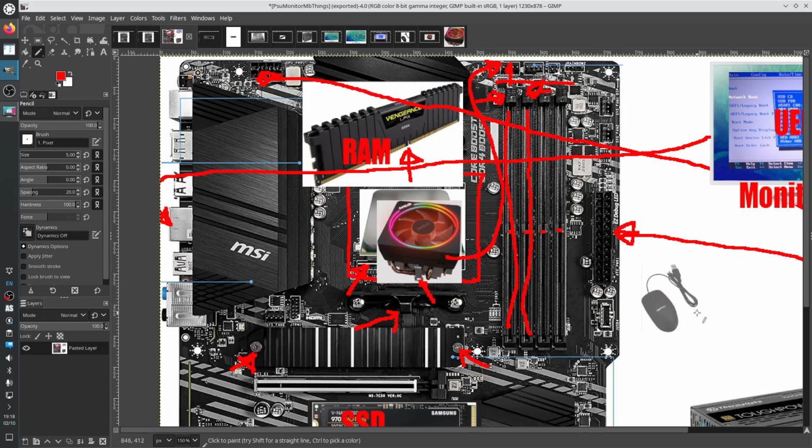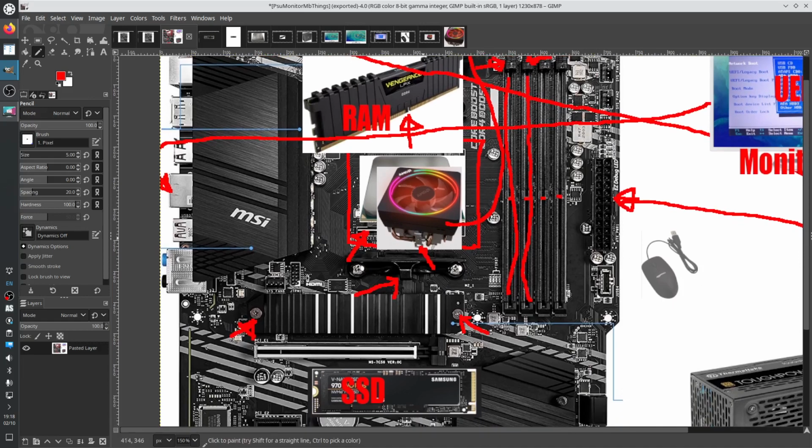Okay, and now you have a computer that, even if you use it, will not get too hot, because this radiator is really powerful for this CPU. We've put just a 35 watt CPU, and then if needed, the fan will start to spin. So this fan does nothing if you configure it to not spin while the CPU has a temperature of 0 to, I don't know, 70 degrees Celsius.